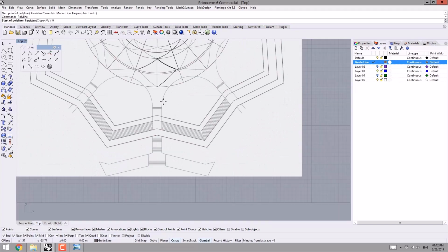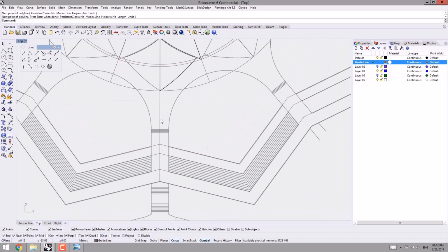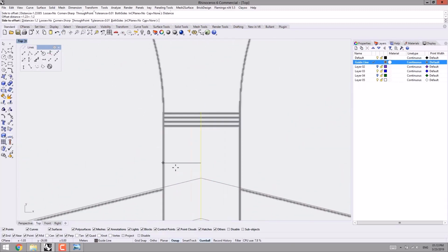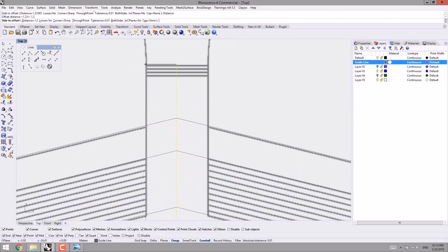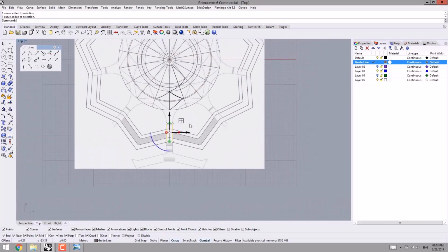So to do this, I open top view, polyline from the origin point till this end point. After that, by using offset command, here I can select this line. I want to split it by this way. Check this out. Following that, I start the command of offset. I select this curve or line, then I specify the offset distance 1.2, and then at both sides. Watch this, we got it at both sides.